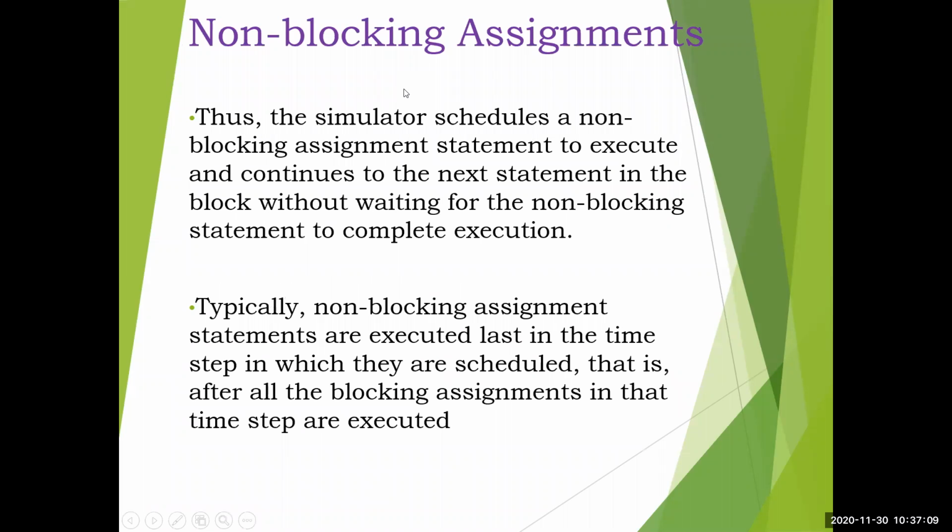So the simulator schedules a non-blocking assignment statement to execute and continues to the next statement in the block without waiting for the non-blocking statement to complete execution. Typically, non-blocking assignment statements are executed last in the time step in which they are scheduled. That is, after all the blocking assignments in that time step are executed. In case you write that, this is how it is going to be interpreted.